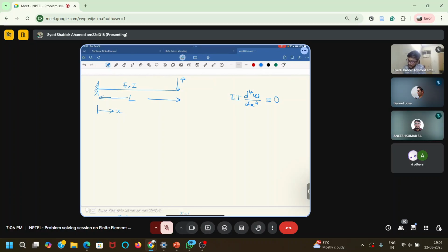So this is the governing equation of a beam. In order to satisfy this, your governing equation should be 4 times differentiable. Earlier the requirement was 2 times differentiable, like the strong form for a bar problem, because for a bar the equation of motion will be like this, right? So for a beam, 4 times differentiation happens to W.